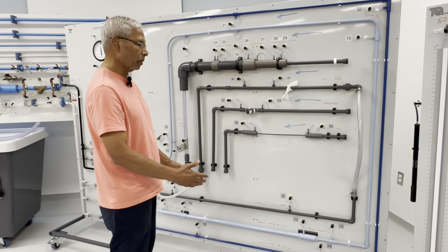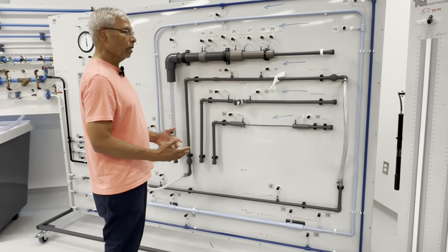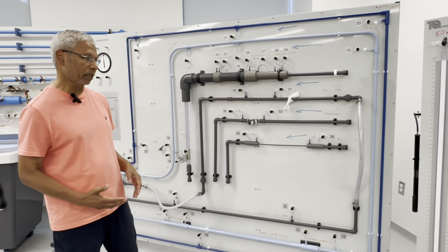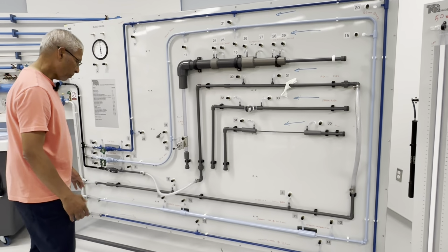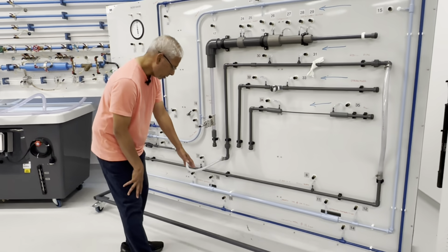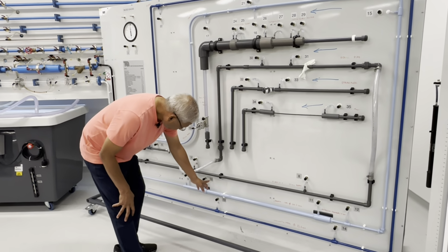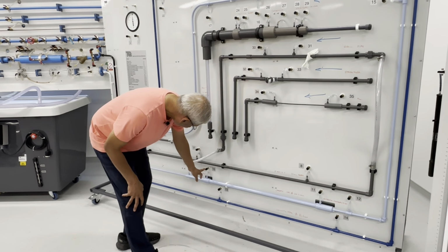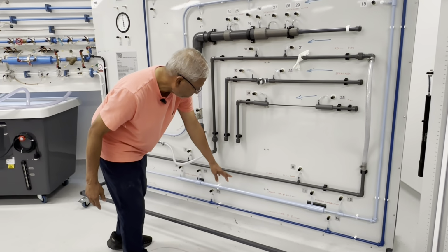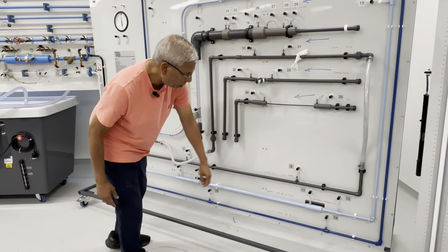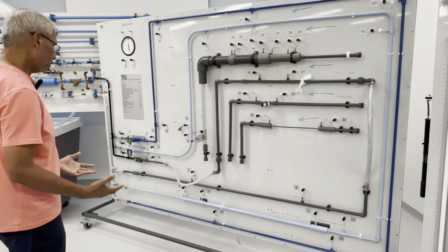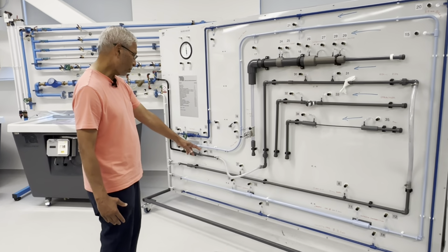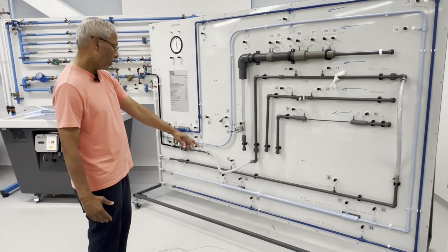As the flow is going through those lines, to measure the friction, you need to know the pressure head loss between those 2 points. And that's where, for example, in a blue pipe, we are trying to tap, I believe, 10 or something. The note tells you what it is, and then the other tap is on the other side. We use those taps to measure the friction loss in that pipe. A little correction, we're using 10 and 11.